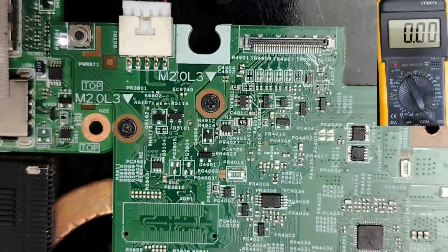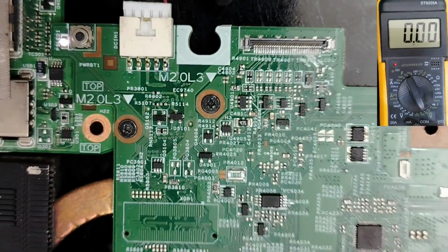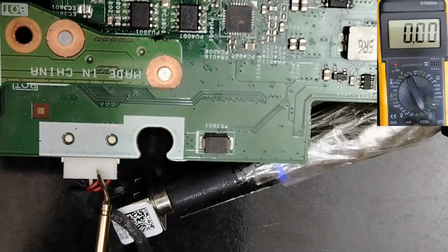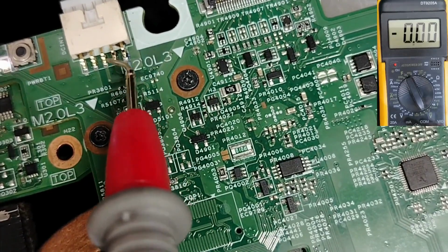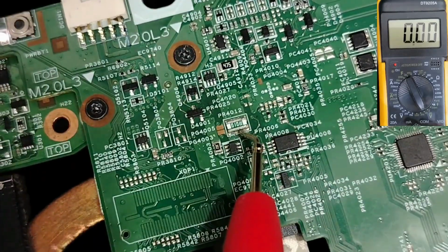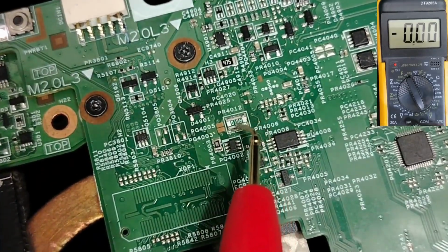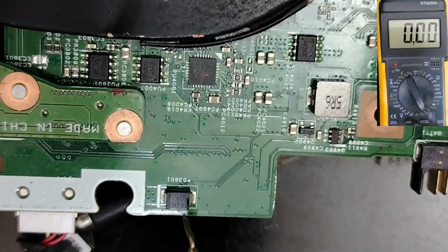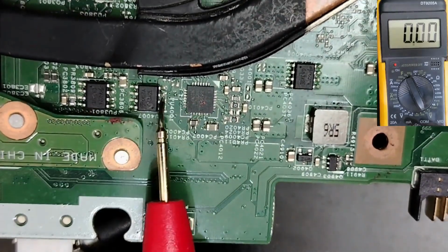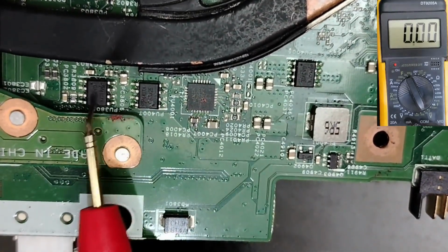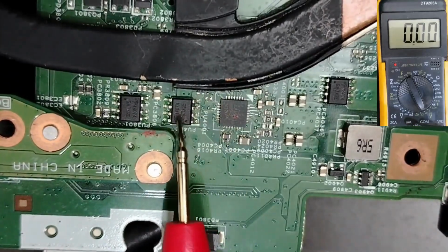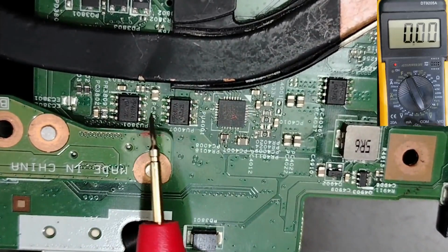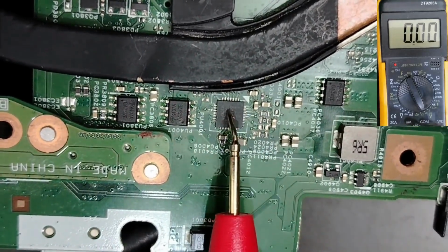Step number 8, guys, is the 3 volt, 5 volt circuit. So we check the power jack. I told you to pay attention to the DC jack in the input connector. Pay attention to this current sense resistor. After that, protection components, switches. Of course, for some boards you can find just one switch. Charge IC. So if you get the control signals in these 2 switches, it means the charge IC is good.